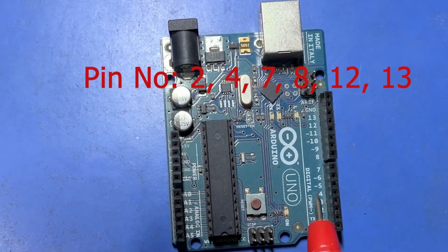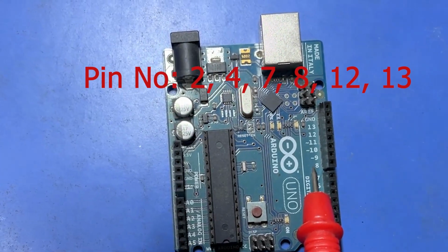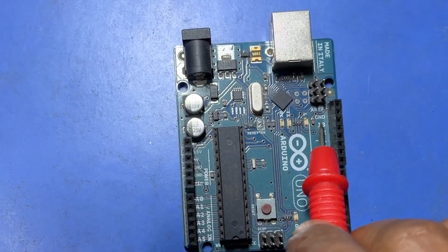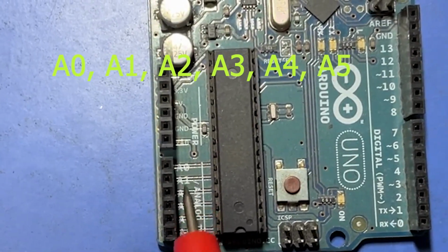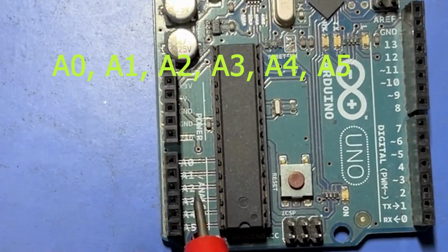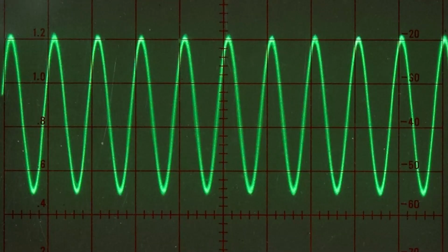We can do read-write operation on this pin with digital output, that means this pin can be either low or high. Second type of pin is analog pin. In this pin we can read-write any values, unlike digital pin. But question is, can we really read or write any value? No. Why? Because analog value can take infinite number of values.